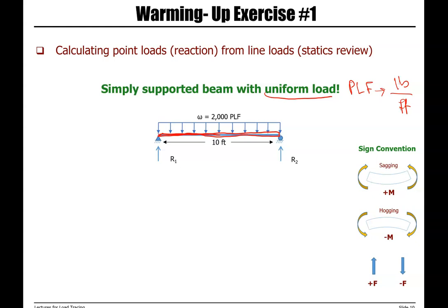The question is asking you to calculate the point loads or end reactions, which are R1 and R2. So we are looking for these end reactions. In order to solve this problem, we can use sigma Fy equal to 0.